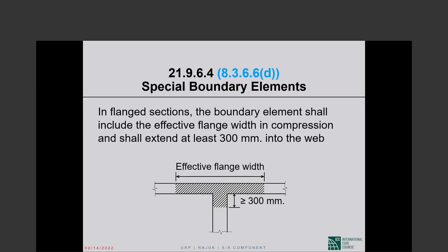So the framing will have beams and columns. The shear wall will go up as far as it needs to. If it is discontinued, then where there was a shear wall, you will now probably have two columns going up. Why would you put a beam on top of a shear wall?